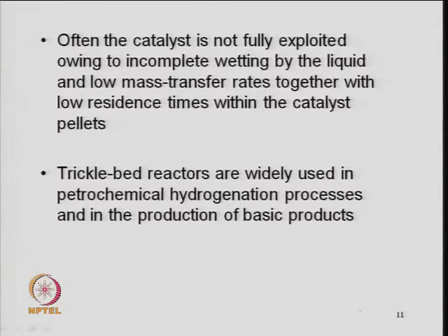So, that is again important, that how wetting and wettability should be correlated, and accordingly the pressure drop will also be affected because of this wetting and wettability, viscosity and phenomena. So, that will affect here. Everything is related here. So, a lot of R&D is still being done or required in order to study the catalyst in a trickle bed reactor for different hydrocracking and hydrotreatment reactions. So, this is one important issue.